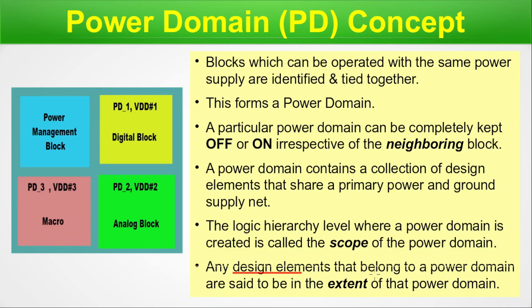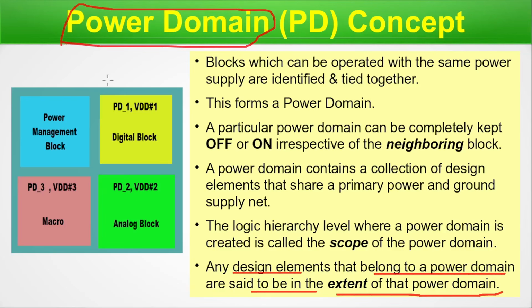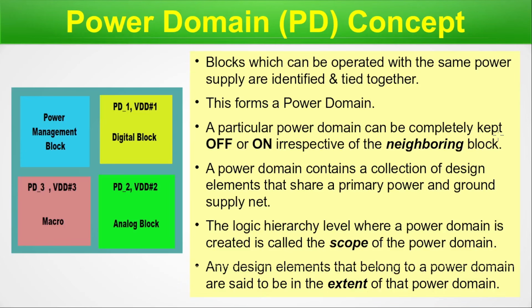Any design element that belongs to a power domain is said to be in the extent of that power domain. So these are typical terms you should remember when you are dealing with a power domain. So there is a scope, there is an extent. Okay, you should be very much aware of these terminologies. So here we are done with the power domain concept and the power management block, that is PMB or PMU.